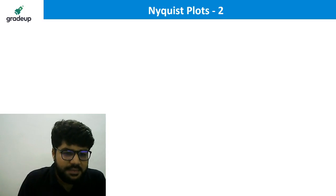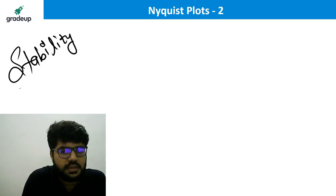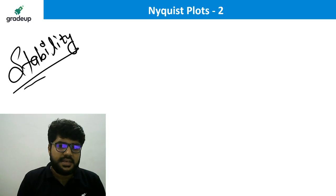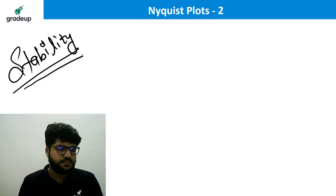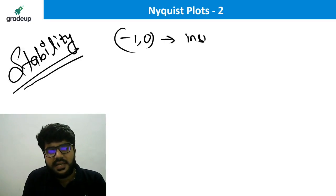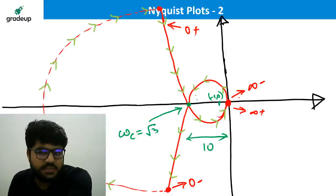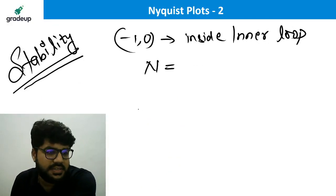Let me complete the stability analysis also. Okay. Yes, guys. Stability analysis. It is clearly seen that minus 1 comma 0 is inside the inner loop. Actually, there are two loops running. It is inside the inner loop. This one, the small loop, the small circle. What is the number of encirclements?